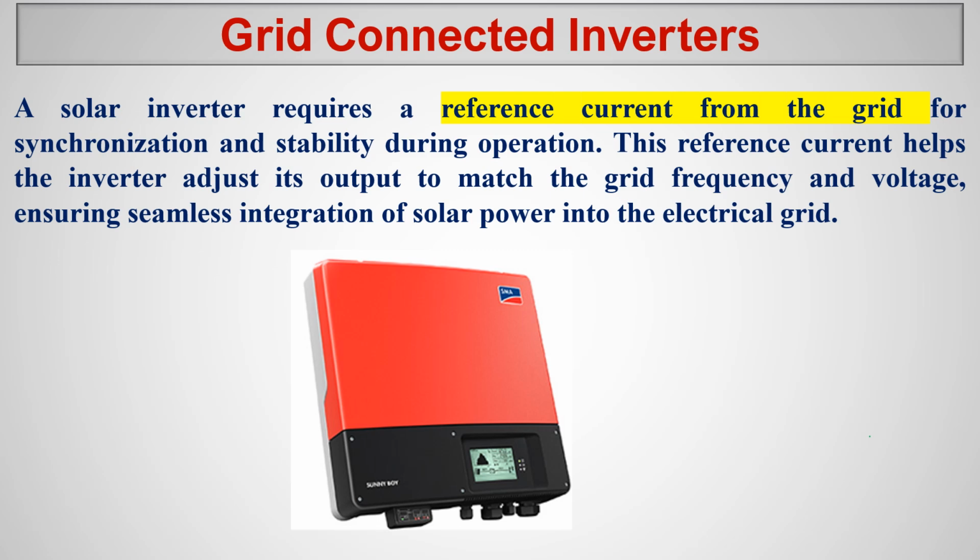So your house cannot get any energy from the solar panels in the daytime, because solar panels produce DC current but it cannot be converted to AC, since this inverter needs a grid supply to operate. It starts its operation only if we have a grid supply. If we don't have a grid supply, then this inverter is dead.